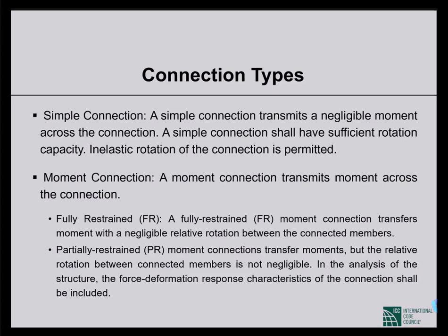So in this case, we have to ensure that the connection has the rigidity for the amount of moment that it is supposed to transfer, and the relative rotational capacity should also be ensured.